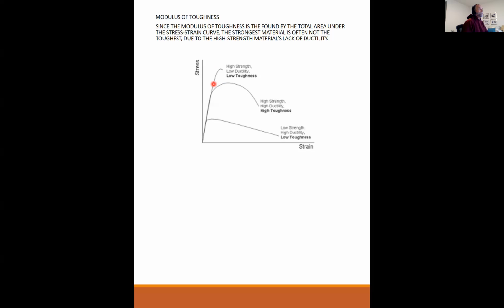Just to put some context in this, regular structural steel that you see in bridges and buildings nowadays is about 50 KSI. That's the stress at which it starts to yield. This strand material has a fracture point of 270 KSI.